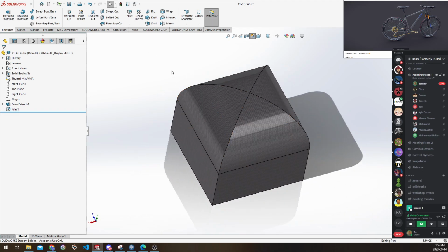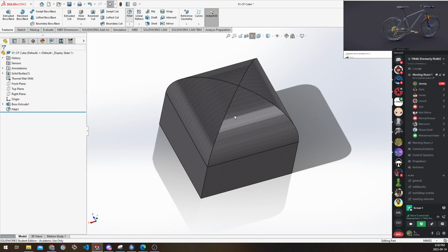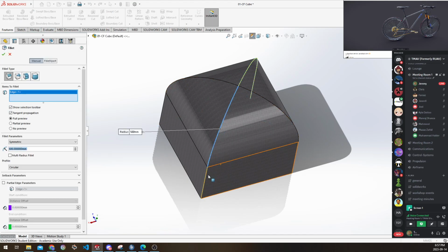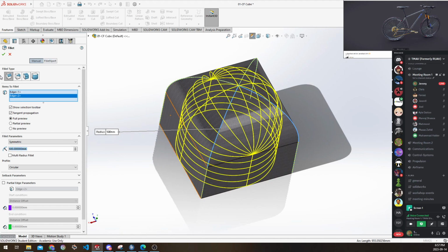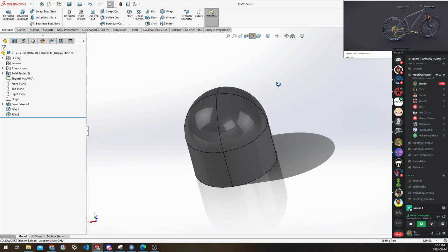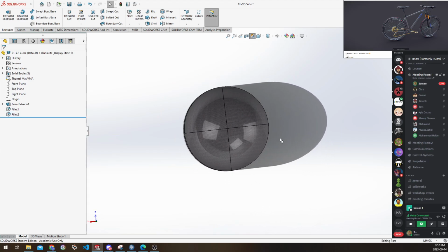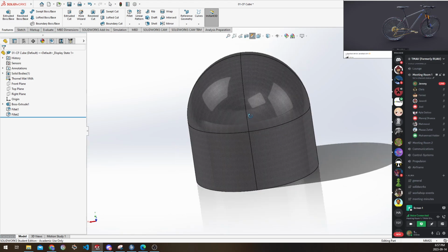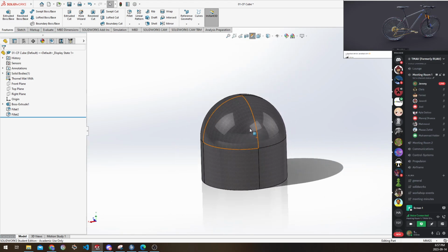It's also important to note that you can fillet again, right? So I can now go back to this shape, and if I wanted to make this fully round, I can now click on these edges here, right? If I hit this again, now we have this shape. Okay, so until your part is fully round, you can just keep filleting something. So it's an easy way to make kind of lazy parts.